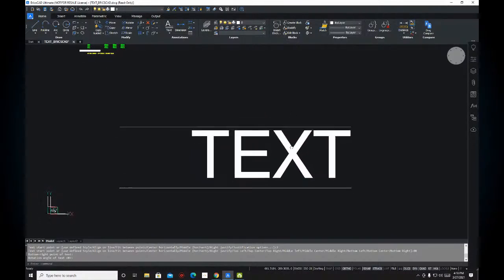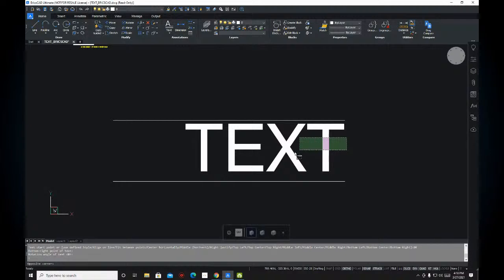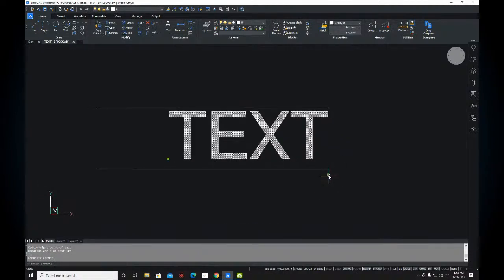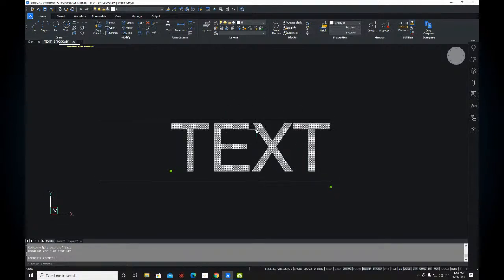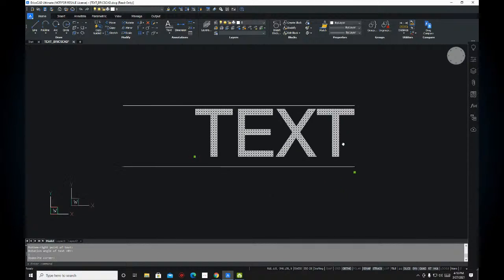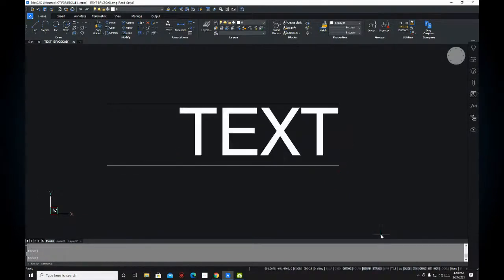Then, did you know that your justification will serve also as the handle if you are going to move this object properly using an entity snap in BricsCAD? For those who are familiar with entity snap, this is equivalent to the object snap in AutoCAD.